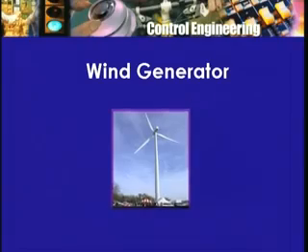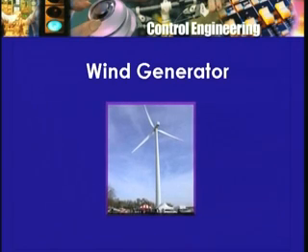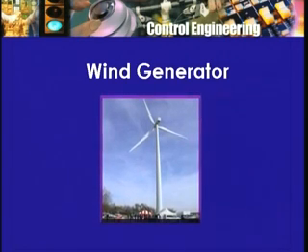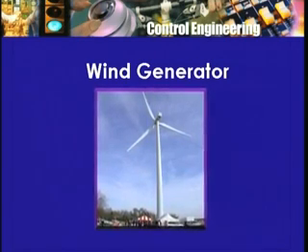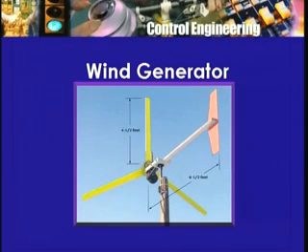There are in our country now commercial wind generating stations where the generator is connected to the windmill, and so it's the wind which propels or moves the generator. There, as I mentioned earlier, there is a control situation because the wind speed can vary, the wind direction can vary, and you would like, once again, if possible, to maintain the speed and the frequency and voltage constant.